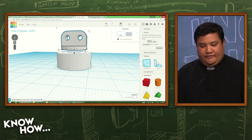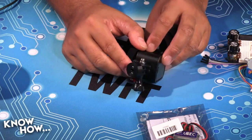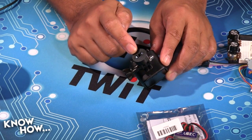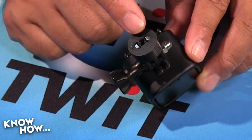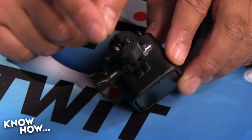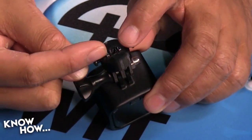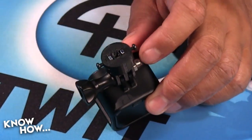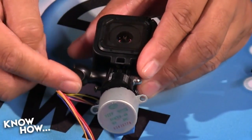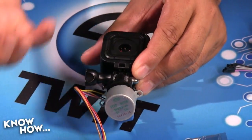Let me show you what that actually looks like in real life. If you go to the side view, Alex, this is the piece that I created. I don't know if you could digitally zoom on that. What I did is create 3 chambers on the bottom of anything that's going to attach to a stepper motor. In the 2 chambers on the side, I put a standard M3, that's a metric, nut. Then I put these holes on the side so I can put an M3 bolt through it, and it will squeeze the shaft. The shaft goes in the middle. That's where the stepper motor shaft goes. Then I can tighten these screws against the nuts inside, and they'll press on that shaft and hold it nice and tight.